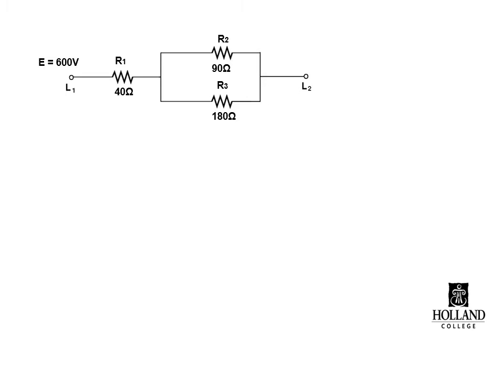So R1 is sort of in series with R2 because some of resistance 2's current comes from R1, but some of resistance 3's current comes from R1. So they're not directly in series because they do not have the same current. Visualizing how the current flows in a circuit will help you analyze the relationships. So we would avoid doing anything with R1 to start with.